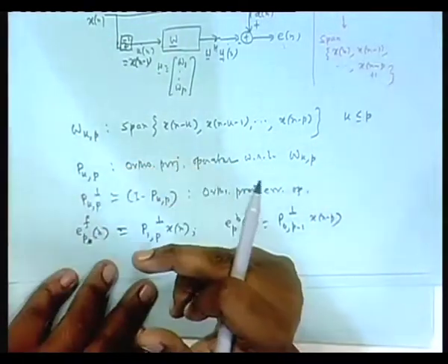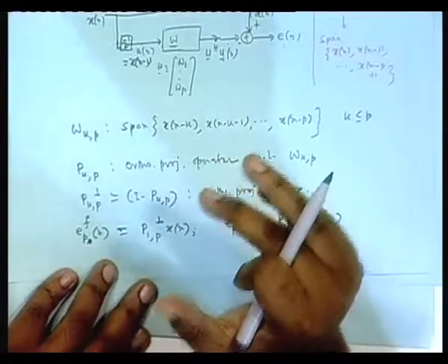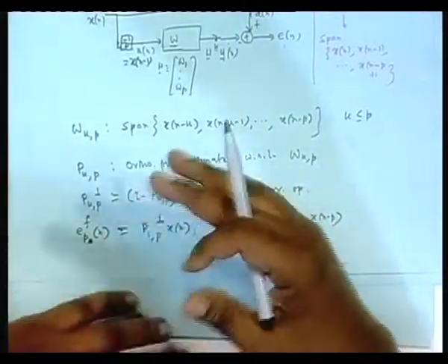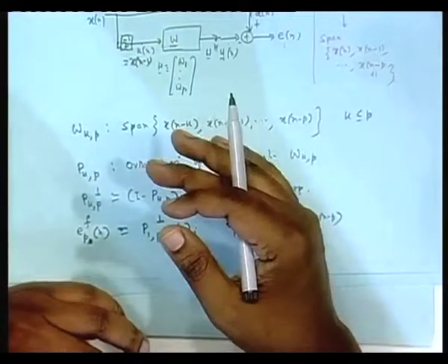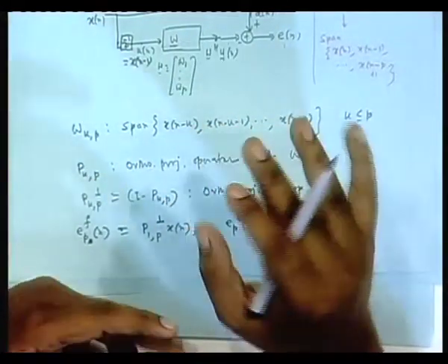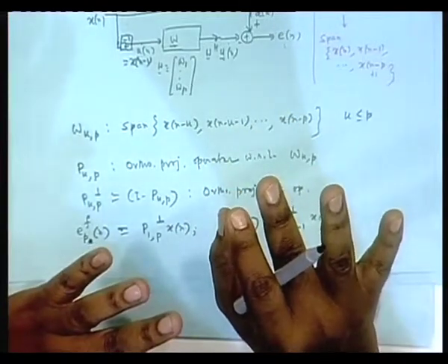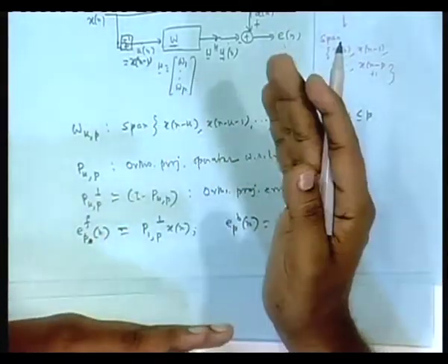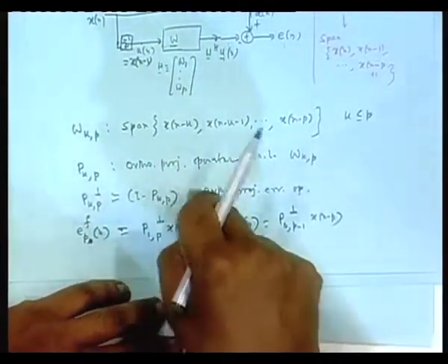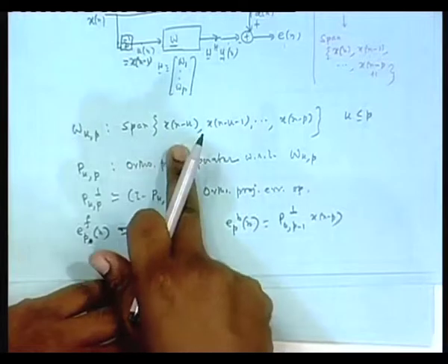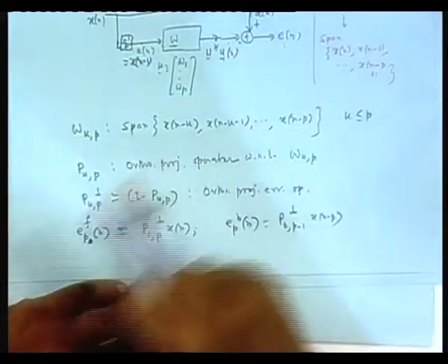So, I will take the mod square, or the quantity multiplied by its conjugate, and there you take all the terms, you will get a lot of correlation terms, but because of stationarity all n will go away. Are you following me? I am not showing that, you should be able to visualize. I am writing this as xn minus a linear combination of past terms xn minus 1, xn minus 2 up to xn minus p.